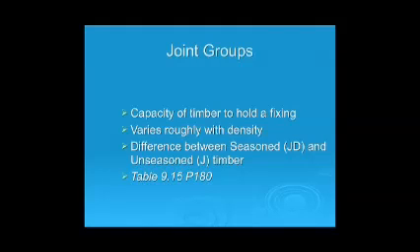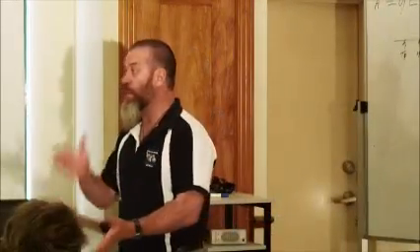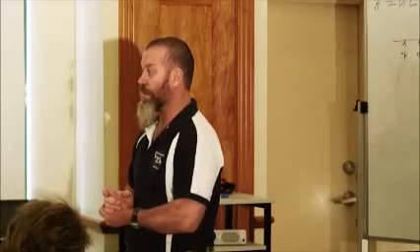Okay, if you were to do a timber wall frame, what would the framing be? 1945. Yeah, hardwood? Pine. Okay. Now this is important. I want to make this distinction. Which joint group do you reckon governs in that case, the pine or the hardwood? Exactly. The weakest joint group governs. If you're using pine frames, we work on JD5, okay?